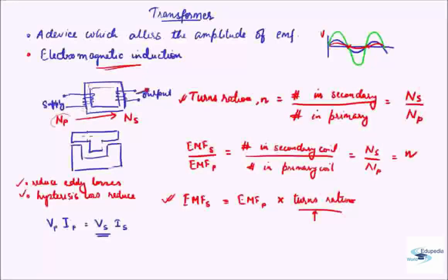In the case of step down transformer, since the voltage of the output is less, the current at the output end is more, therefore the output end or the secondary coil should have thicker wire. Okay, I hope you get this concept. This is a very important practical concept in designing a transformer.